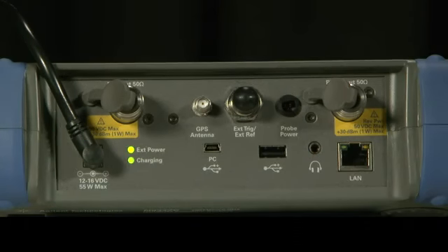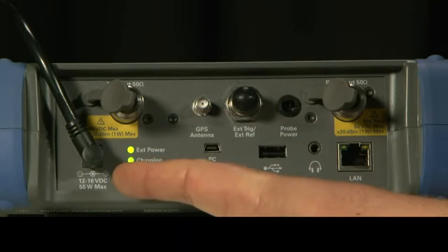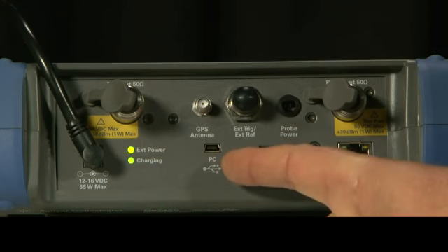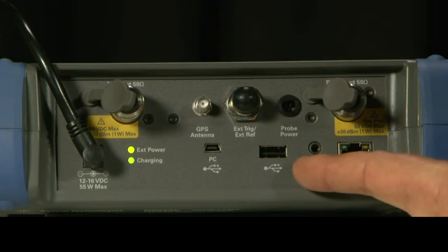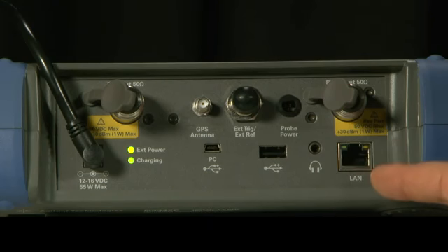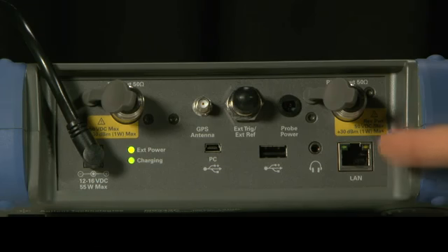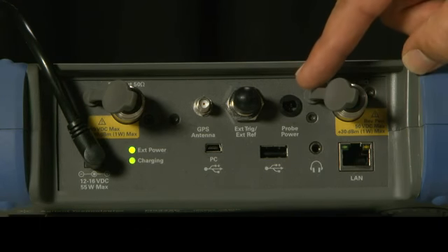On the top panel we have the main RF input, the DC jack for externally powering the instrument or charging the internal battery, a small USB connector for connecting the instrument to a PC, a large USB socket for a USB memory stick, audio headphone out for listening to demodulated audio, an Ethernet connector to connect the instrument to a local area network, an RF output socket if you have the internal tracking generator option installed, a probe power socket